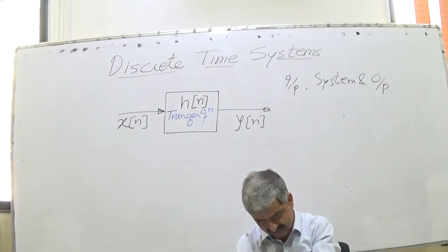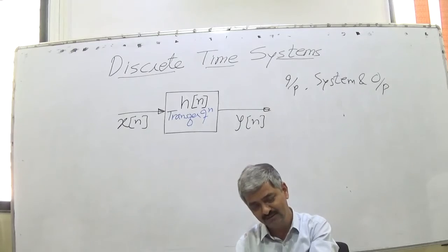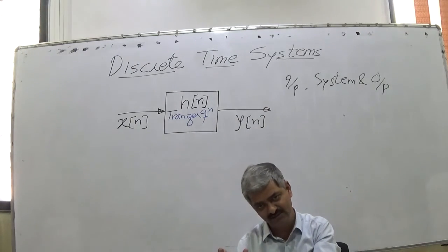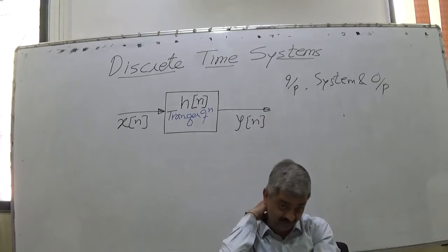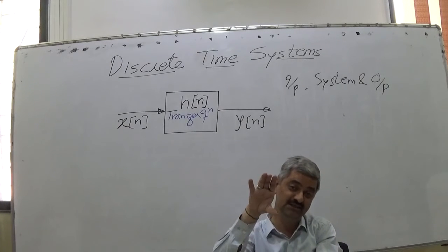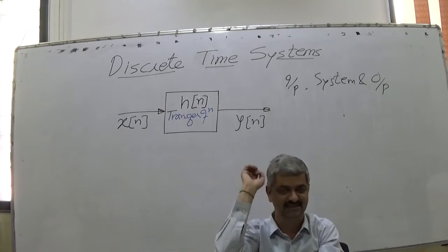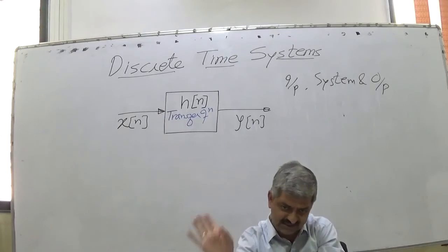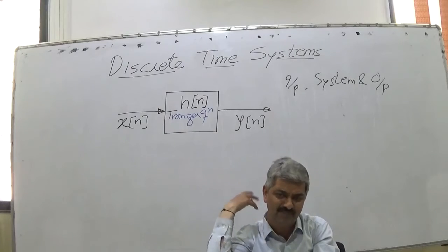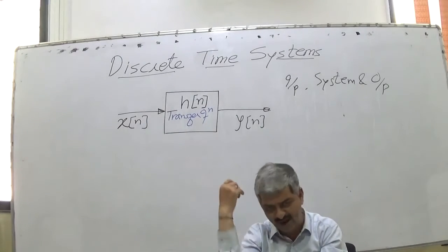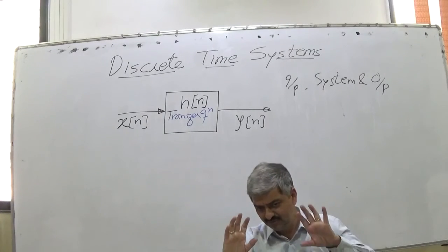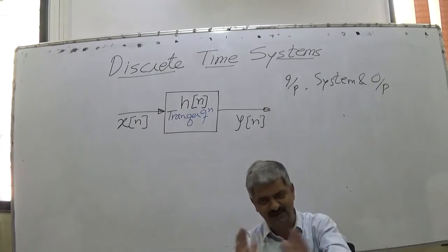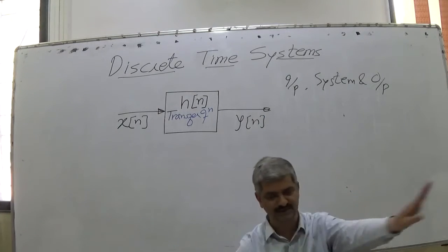In those days it was not possible to sample at a sufficient rate, so whether that would have some impact, and I would not be able to convert analog to digital signal. 8-bit ADCs were built, but now 32-bit ADCs, 64-bit ADCs and sampling at some megahertz rate is quite easy. So the effect of sampling error and quantization error is just negligible. We ignore that now.